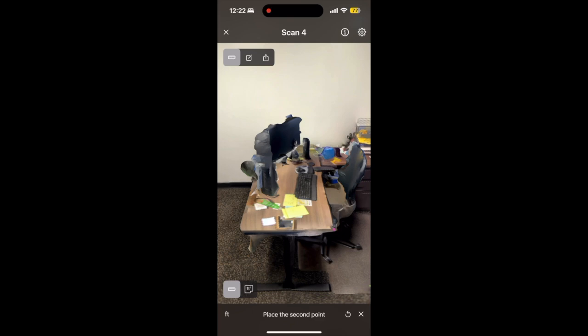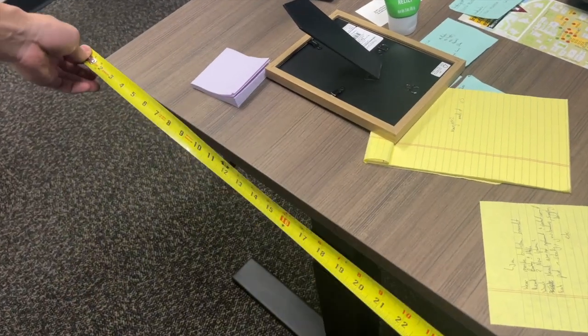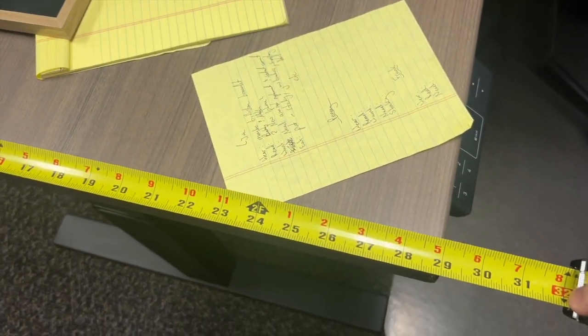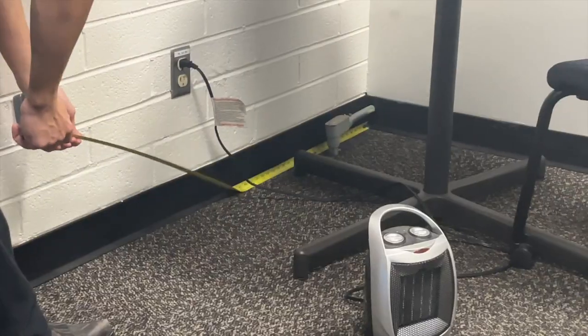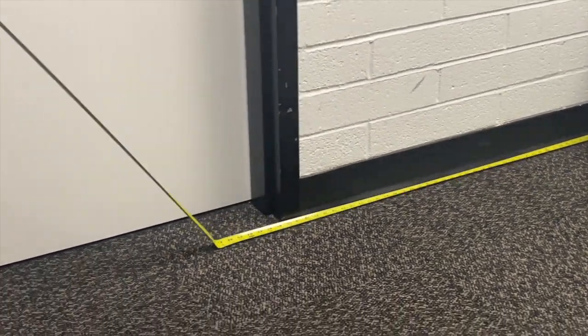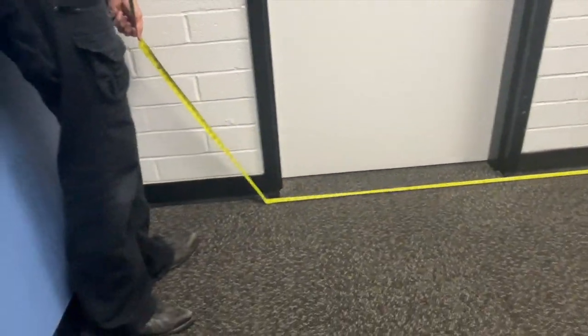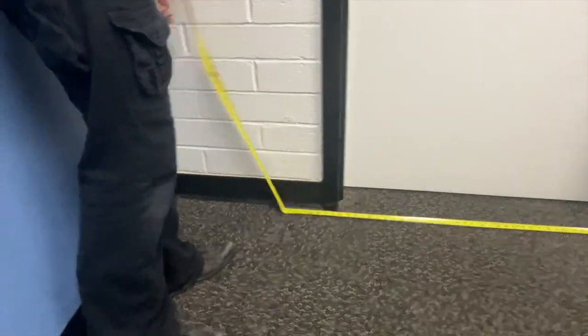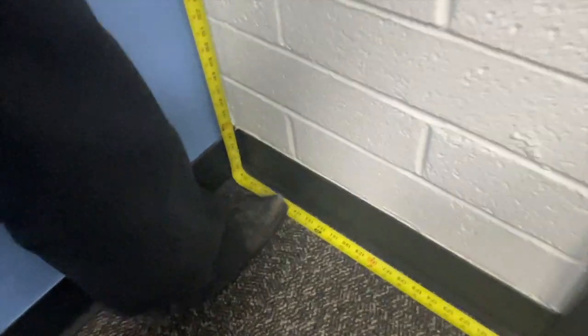Now, before I'm ready to leave the actual area, I'm going to go on the app and use the measuring tool to actually compare the measurements on the app to what I'm seeing in real life. Now, assuming you have the correct conditions, you can have an accuracy of up to 3 millimeters or so. I'm getting a margin of about half an inch, but this is going to be information that we need to keep for when we decide to scale up the objects in AutoCAD later on.